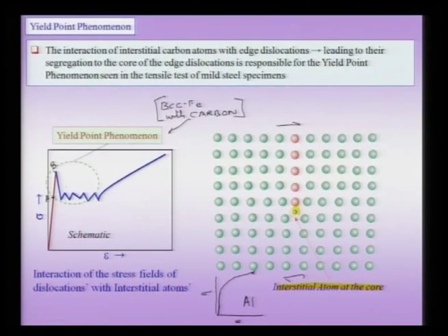and of course repeated locking in this atmosphere can lead to a phenomenon known as serrated yielding. So, there is a serrated yielding, and once the dislocations are free of this Cottrell atmosphere, then the stress strain diagram looks rather smoother. So, the entire presence of this yield point phenomena is because of this interaction of dislocations with the point defects, in this case carbon in BCC iron.